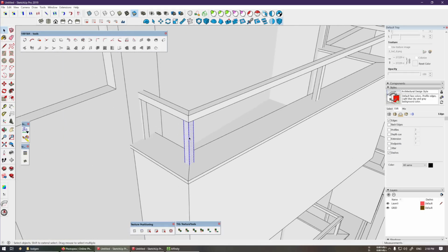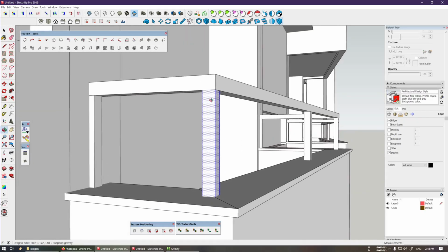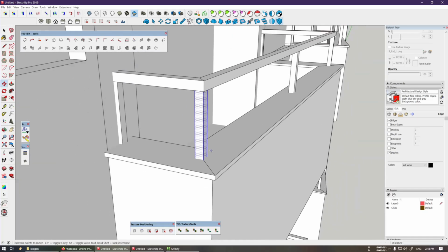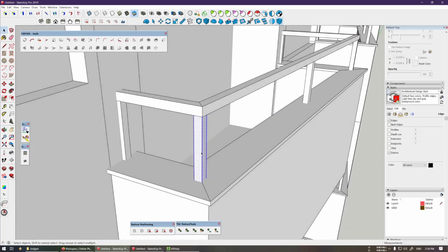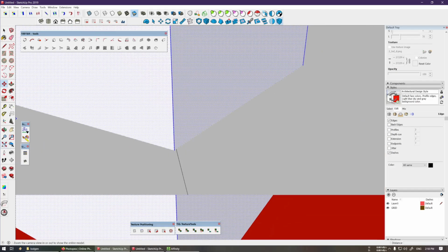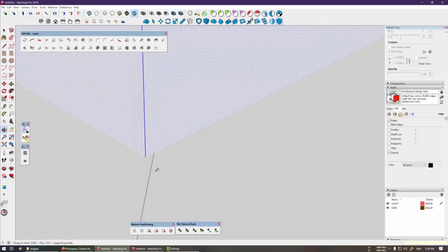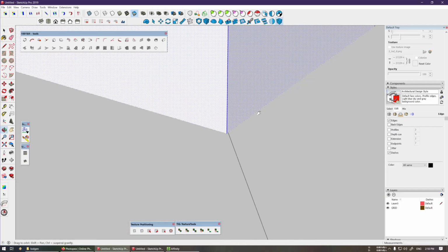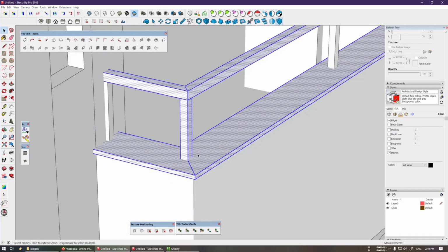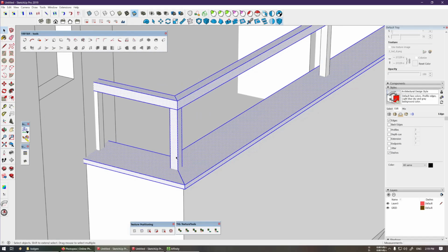Let's say this railing here is completely isolated from the rest of the model. They are not touching, they are merely clipping through. If I zoom in really close, you can see the corner is not even touching the other lines. However, if the line is touching other lines, then you've got a problem. This thing is merged together and extra geometry will be created, increasing your tri count. So be careful about that.